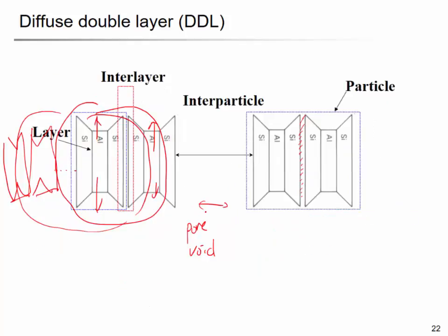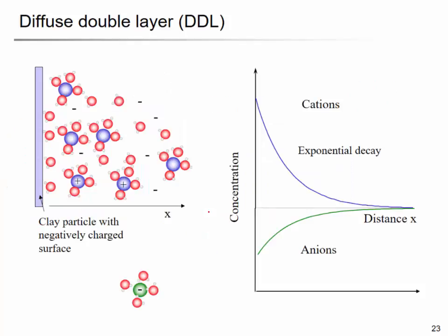And in clay, when you add water, you develop the adsorbed water layer, right? Or we call it the diffuse double layer. And that's because of the negative charge on the clay surfaces. So clay itself is negatively charged. So electrically, it's not neutral. The balance is actually broken. So you have to have a cation to balance it.